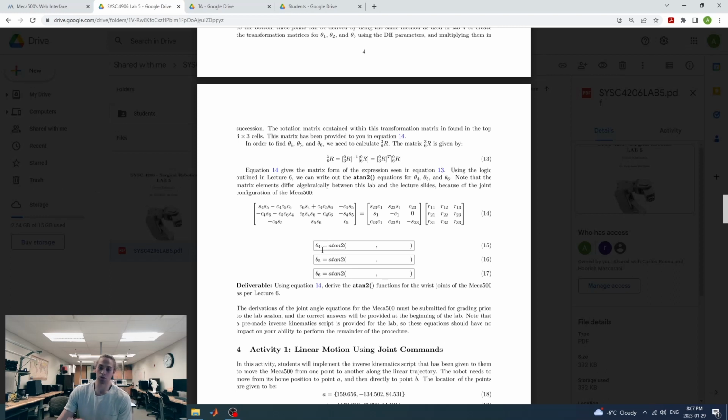You can take two elements and divide them so that one of the terms in each element will cancel out, and the other two terms contain the same joint angle but have either a sine and a cosine or a cosine and a sine. And that will allow you to create a tangent function, which you can then go over and determine which elements you're dividing by each other to put into these equations here. So that's sort of a tricky one where you've got to cross-reference two sides of a matrix equation.